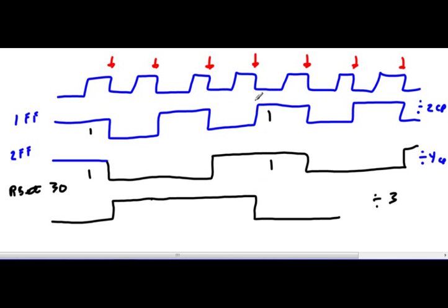down in 3. And now, in order to have 3 states, I need 2 flip-flops. And the reset is in relation to the first flip-flop still? Both of them, yeah. So when they're both high, it resets. Because of the 3, you're never going to see the 3. It goes back to 0, 0. I see.